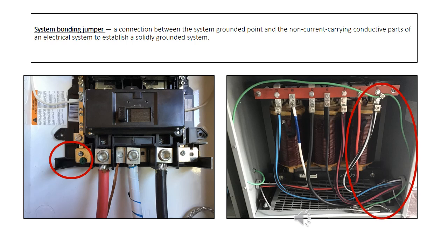In the photo on the right, as you can see, this is a transformer. The grounding conductor terminates at the transformer X0 point, but the green conductor from the transformer X0 to the transformer frame is known as the system bonding jumper and is sized in accordance with Table 16 and Appendix B Note to Rule 10-614, Subrules 1 and 3(a).